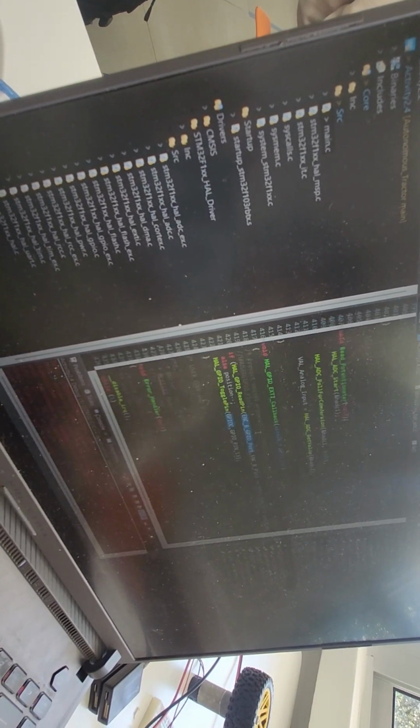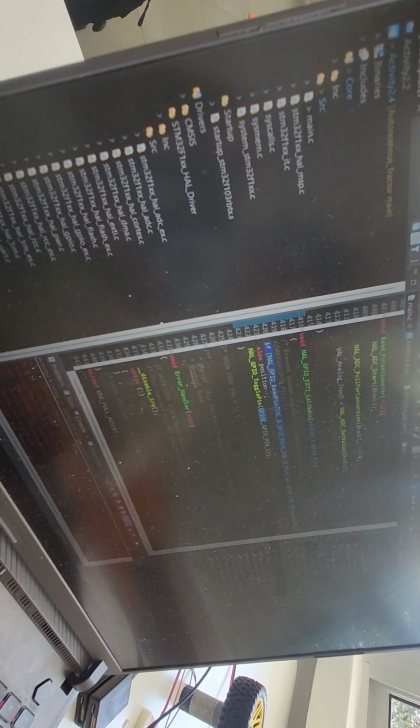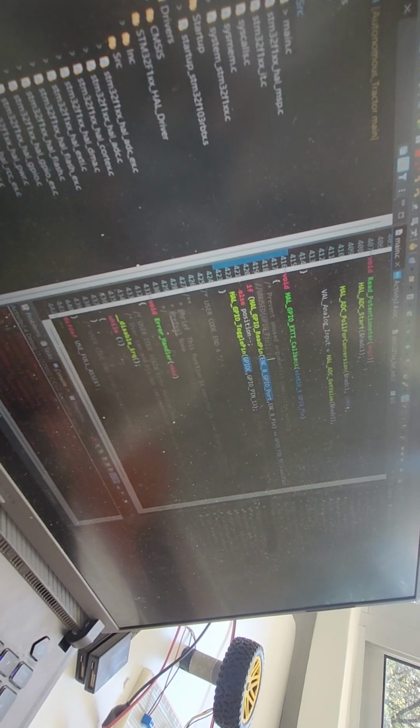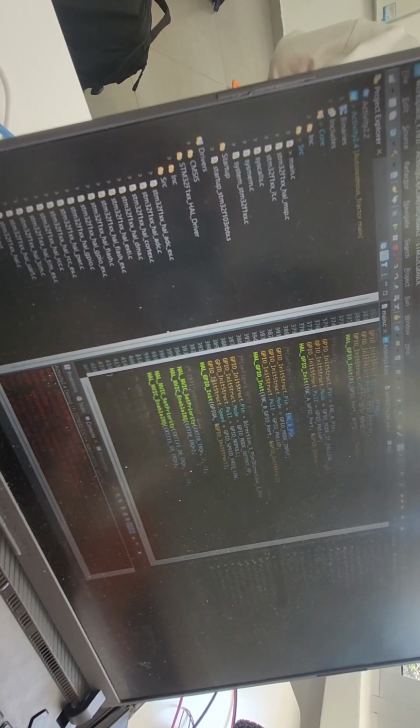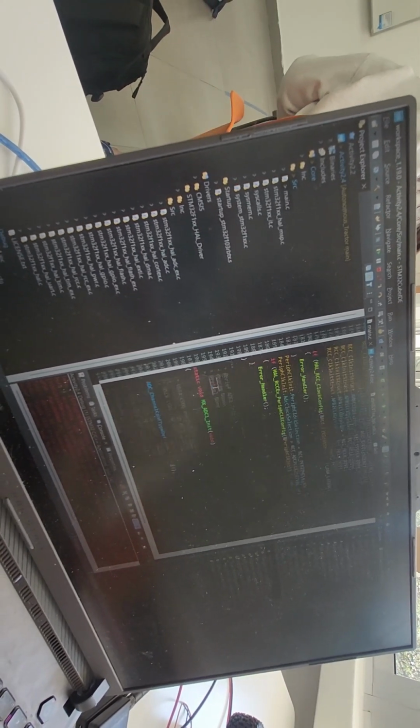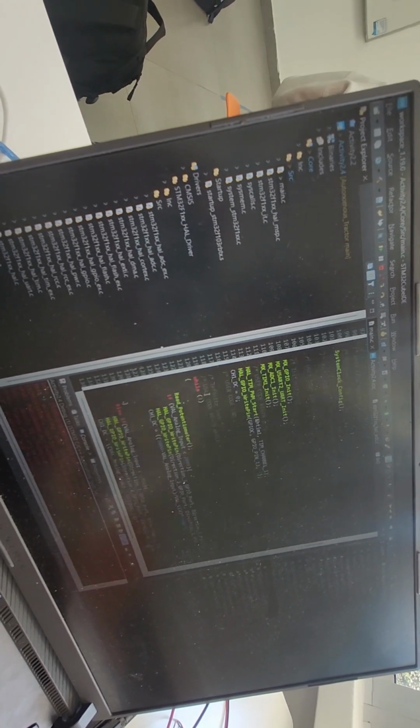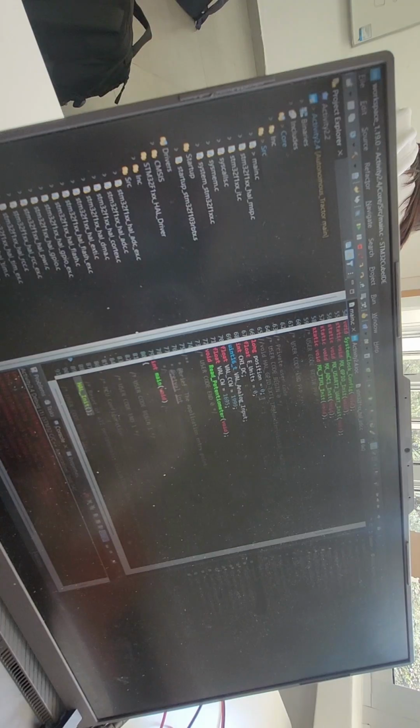Here in the interruption, we are checking what direction the motor is rotating, depending on if the pin of the encoder B is on or off, and then we toggle that position on and off, and that changes the value of the long variable position that we declare here.